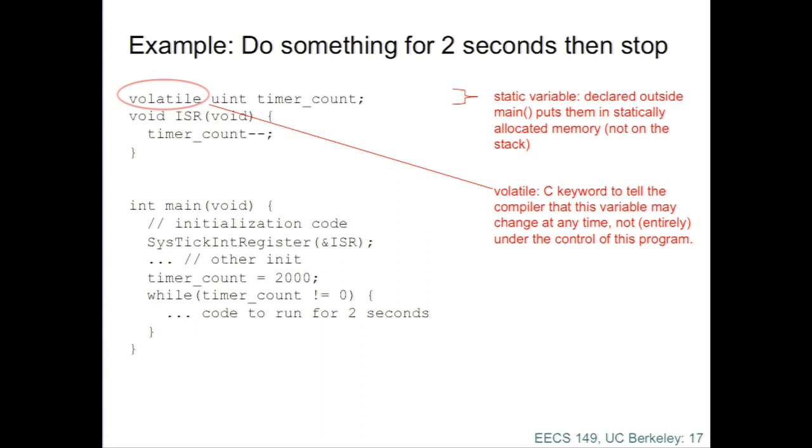So it's a pretty important keyword to not forget, because you might get lucky and your program will work without the volatile keyword, depending on what the compiler does. But you change a line in your program somewhere, recompile, and it doesn't work anymore. The line you changed was in a completely different part of the program, but it somehow triggered a different set of optimizations, and your program stops working for mysterious reasons.